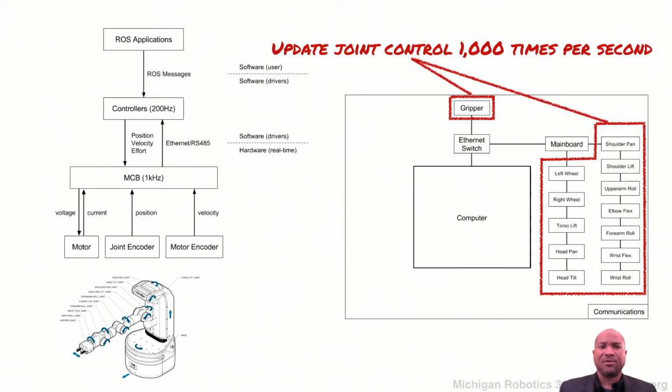And when we're thinking about doing this, we should think about what is actually doing this type of control for us. We can do this control in software. That means that we would have to have some sort of guarantee that the control is happening at a prescribed rate and is happening quickly. Usually we'd use something like a real-time operating system to do that, or some sort of system that provided this. So there are robotic frameworks out there, such as Orocos, that could do this. When I was coming up, we used VxWorks a lot. Linux has real-time kernels that can do this as well.